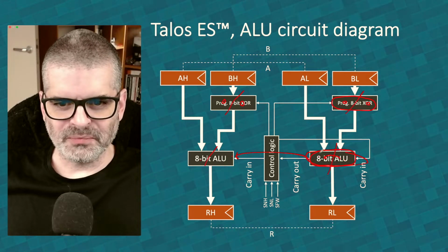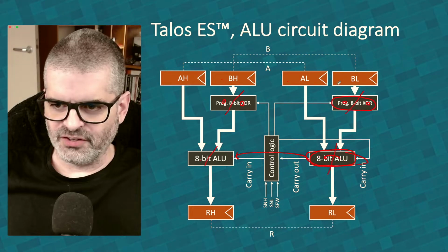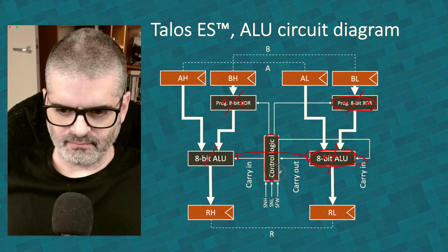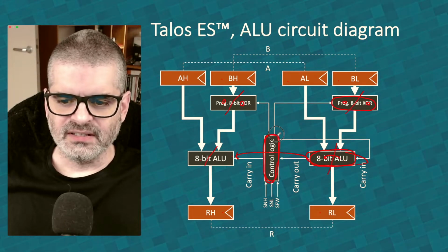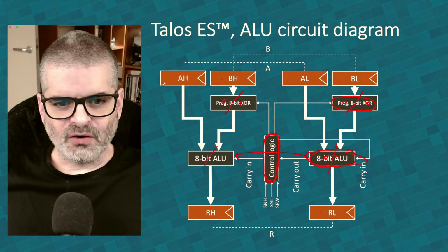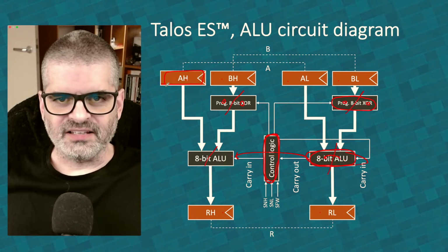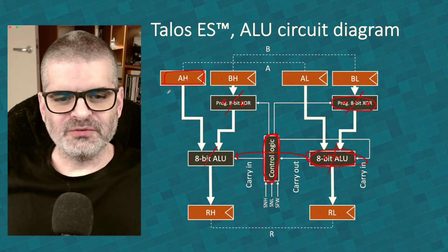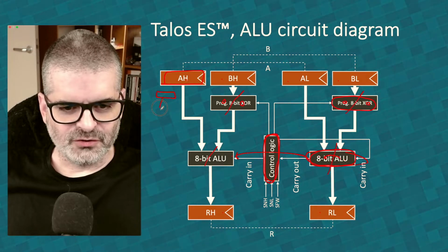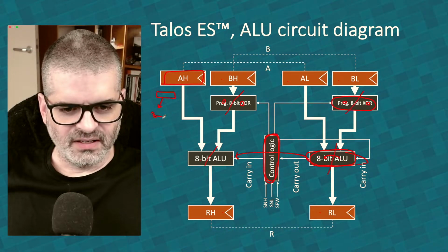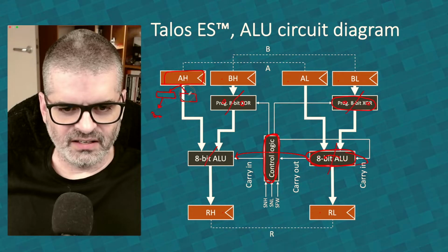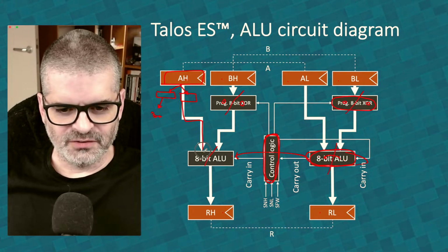So you see the number of chips is multiplying. The registers are all 8-bit registers. It's a single chip per register, so 6 chips. The control logic will require 2 74 logic chips. I'll show you in a moment. And if we want to display the contents of these registers here in LEDs, then it takes several more chips, because we need a driver for the LED. So say a 245 to drive 8 LEDs. And we need another driver. So this goes there and here. And we need another driver to drive the ALU.